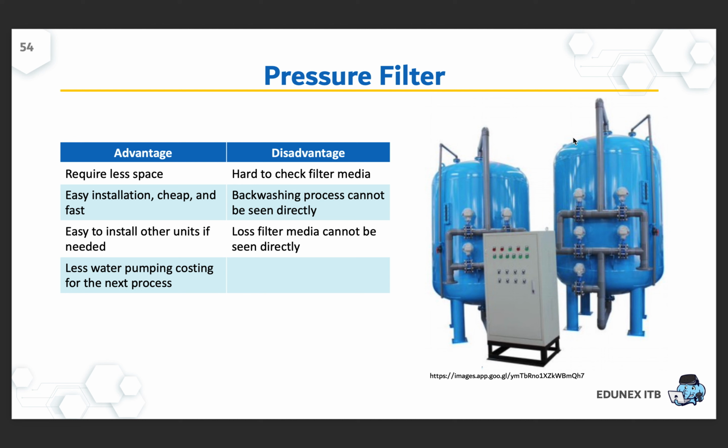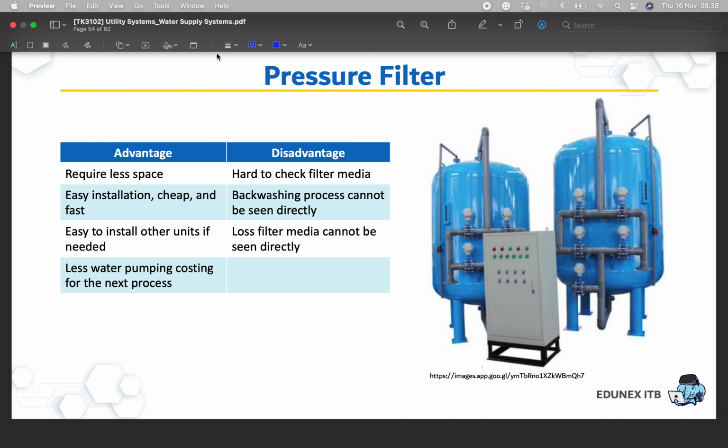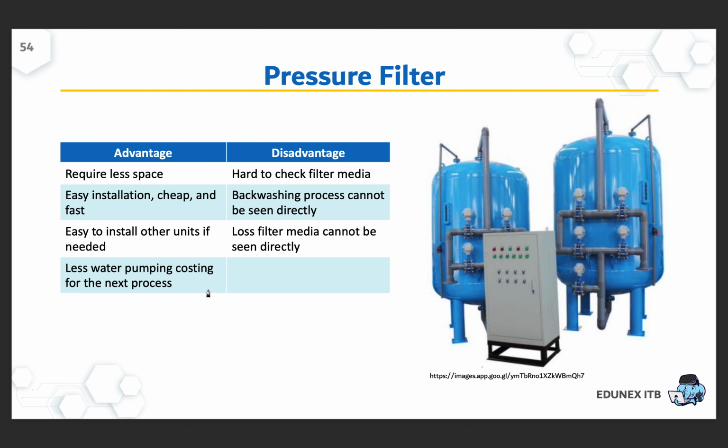And then backwashing. Backwashing is one method to clean the filter. Let me draw a bit here. Okay, so if I have the filter here, the feed conventionally moves toward these directions, and here we get the filtrate, the water. Over time, we will have a lot of solids here on top of the filter, and we want to clean the filter. One method is by using backwashing.